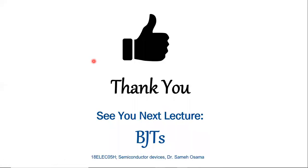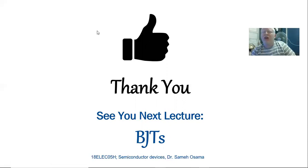Now, this is the end of our lecture. We have finalized now the MOSFET operation. We studied the MOSFET operation from two perspectives. The first perspective was a PNP junction or NPN junction, accordingly, whether it is an N-channel MOSFET or a P-channel MOSFET. And we studied how the channel is created, how current will move from the drain to the source, or how electrons will move from source to the drain. The condition for that, the region of operation. We plotted the ideal and the real IV curve for a MOSFET.